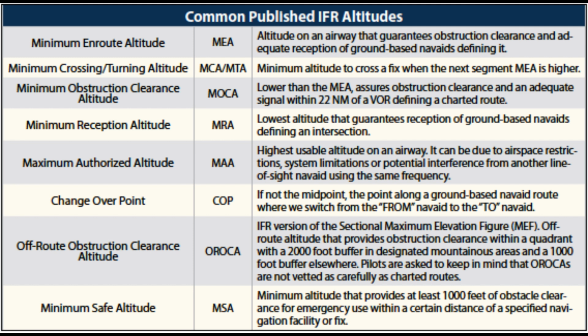RNAV minimum en route altitude. RNAV MEAs are depicted on some IFR en route low altitude charts, allowing both RNAV and non-RNAV pilots to use the same chart for instrument navigation.